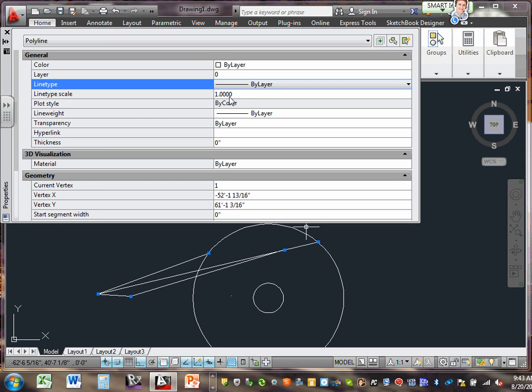This becomes an issue when we draw a dotted line in a parking lot and you see, I grabbed the dotted line, but it's not showing as a dotted line. That's because the scale of the line does not match the scale of the drawing. If the dotted lines are far away from each other and you scale them differently, the gaps between them will not be seen by the naked eye. So when you print them, they wouldn't show up. So you have to go change the scale. We will play with this one as it comes.